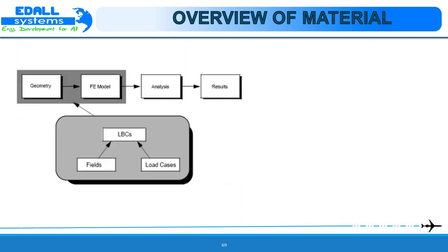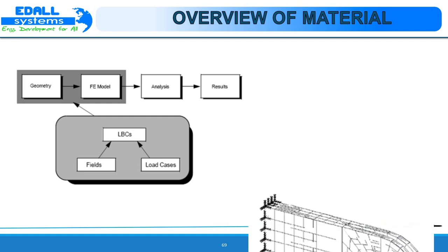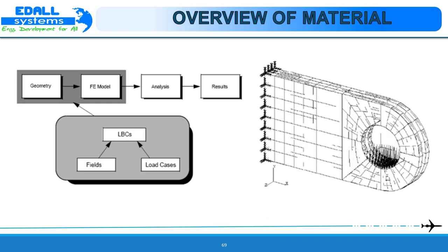Overview of loads. Most analysis problems involve the solution of how the model behaves in response to some action on the model: a force, a pressure, a temperature, or perhaps a magnetic field. In analysis terminology, these actions are known as loads. Similarly, some models have certain conditions constraining their behavior, for example, the end of a cantilever beam fixed on a wall, or an adiabatic, that is, non-conducting, boundary in a thermal problem. These constraints are referred to as boundary conditions. In this chapter, loads and boundary conditions are frequently referred to as LBCs.